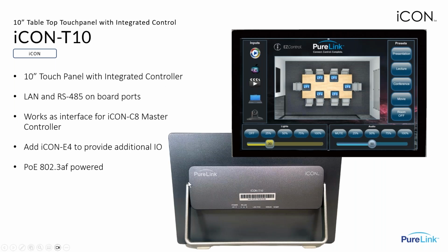All right, so moving on, now we've got our 10-inch touch panel. This one is tabletop. You see the kickstand on here, but other than that, it's very related to the T4W in terms of its connectivity. It has LAN and RS-485 on board, and we also supply you with the converter to use it for 232, and it has the built-in controller.